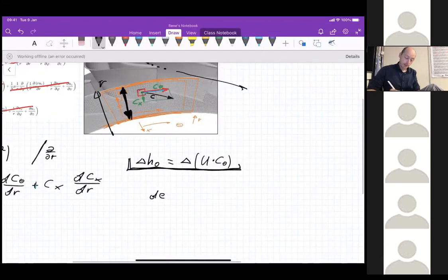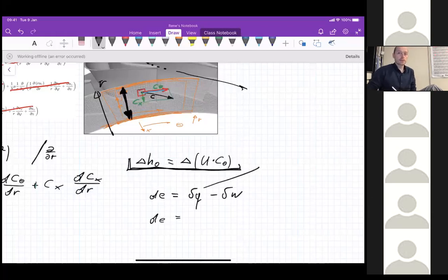No. So the change of internal energy of a system, the total differential of the internal energy, equals the inexact differential of heat that is added across the system boundary plus work, right? And then we know that for dq we can use exact differentials, because dq is nothing else than T dS, right?